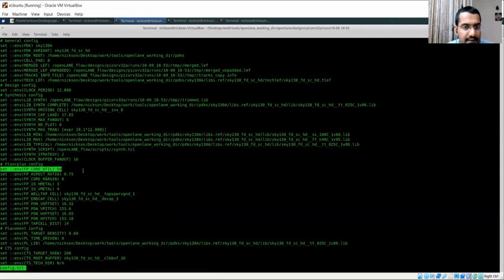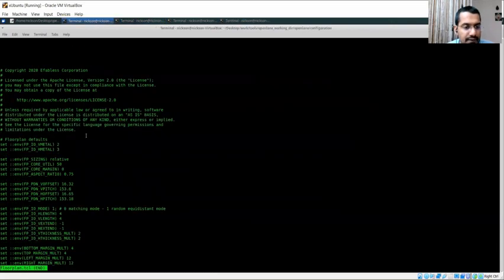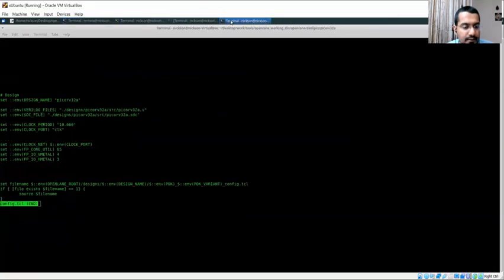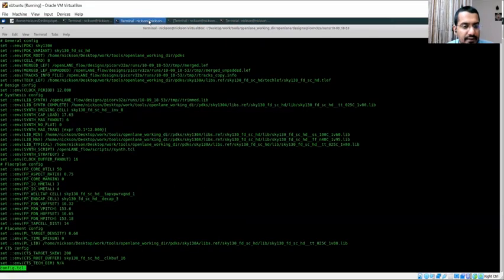This is the default floorplan setting, and in it the core utilization was 50, and in the design config.tcl core utilization is 65. But when we check the config.tcl that was used for the current run, it says that core utilization is 50.